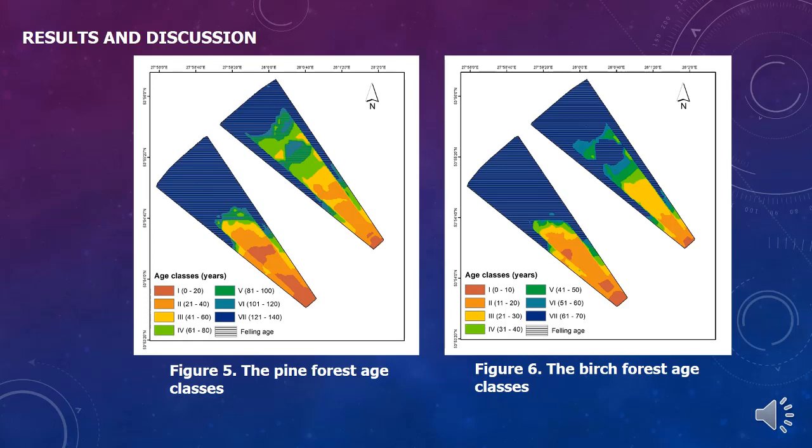When comparing models, it can be seen that conifers grow in height more slowly than deciduous ones. Following the forest reference book, in areas with temperate climate, the maximum tree height is 37.3 meters for pine, and the tree no longer grows. Therefore, where the isoline height exceeds 38 meters, any forest stands can grow without restrictions and the need for monitoring. But in climatic zones with other tree species, it is necessary to take into account their local growth rates and maximum heights. The technology of vertical zoning can be used for many tasks of near aerodrome territory land management, construction of power lines, bridges, road networks, etc.